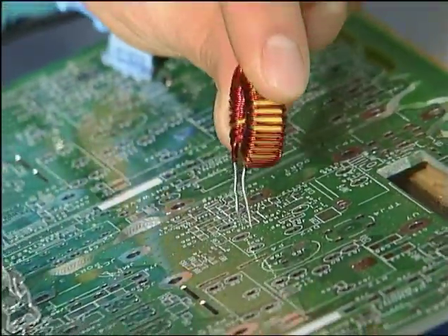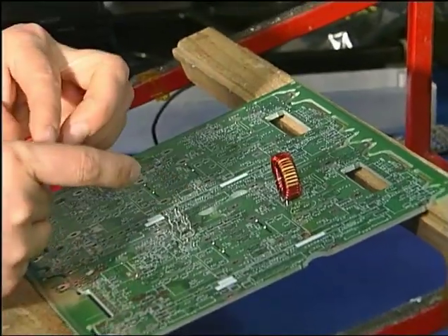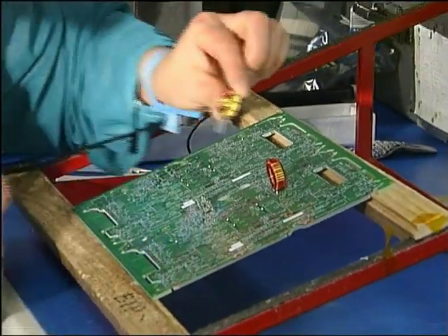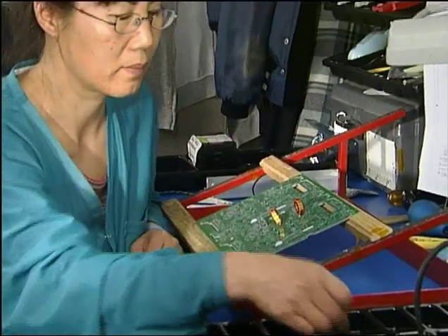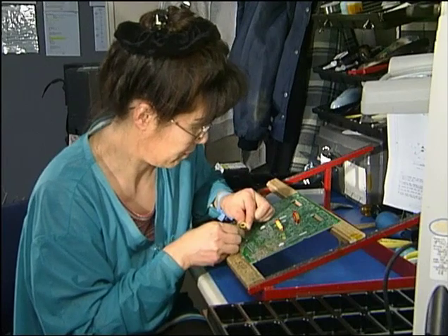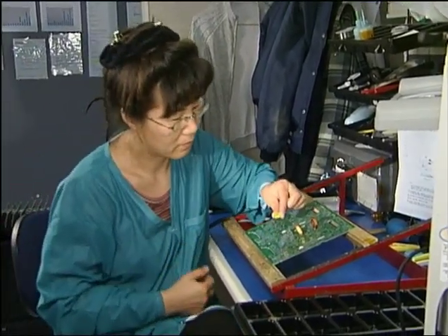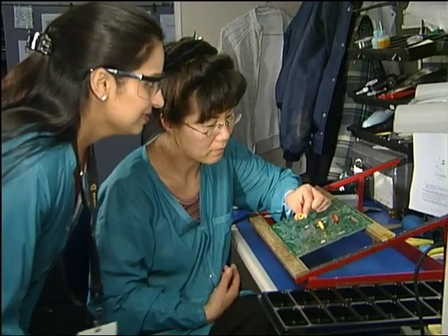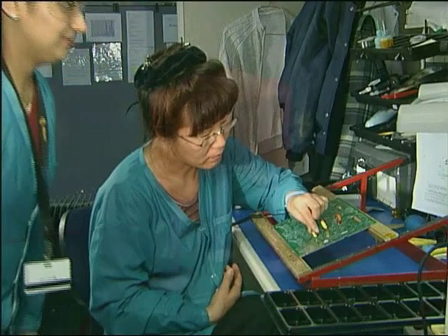Watch out for any coiled components that are designed without that information. Variations in wire gauge, number of turns of wire, wire spacing, internal diameters, numbers of wires, and sometimes the use of ferrite or other types of cores can change the part numbers and values. Check with your supervisor when you have trouble identifying a component.